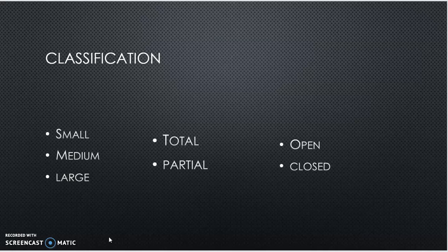Let's say you're constructing a health center. Now the health center plan everywhere in the state of Goa can remain the same. So a person who's prefabricating these units can manufacture this exact same size of beams and columns for one particular plan, because that will be used again somewhere else. So his molds, his casts are being used again. So closed prefabrication system is only justifiable if the size of the project is large.